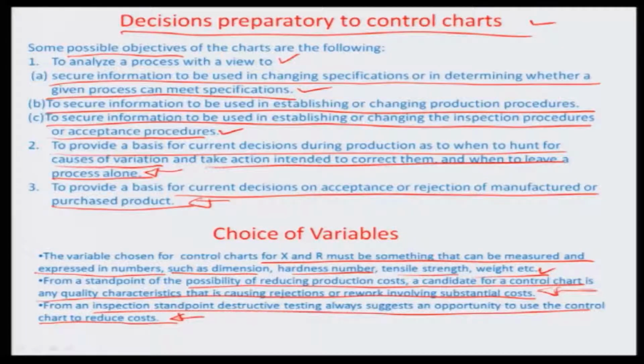That is because you don't want to destroy all the products which are being made. You have to do that on a sampled basis. For example, the ultimate yield strength of a material: you can't get this parameter without destructively testing the sample. So in a production process, if all the samples are measured, you are not going to have anything at the end of the day.